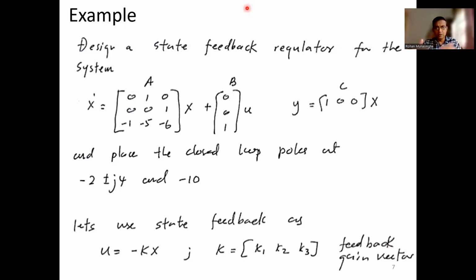You have a lot of relationships between state variables, so that using these relationships, you can remove some of the intermediate variables and relate, say, initial condition and the control signal or the final state, like that, and design an optimal control, right? So that's why these two gains being 3 and 4 is just a coincidence, probably, right? It could have been anything. So there's no such relationship there between K1 and K2. Just for this one, because of the nature of the plant, it came like that.